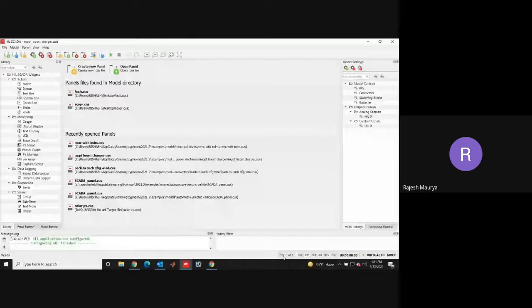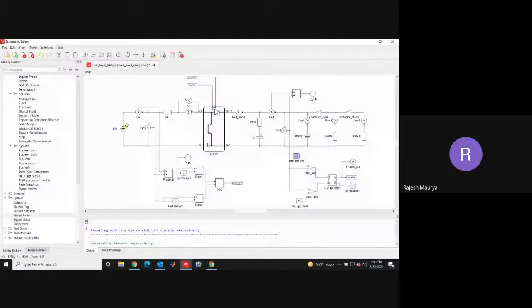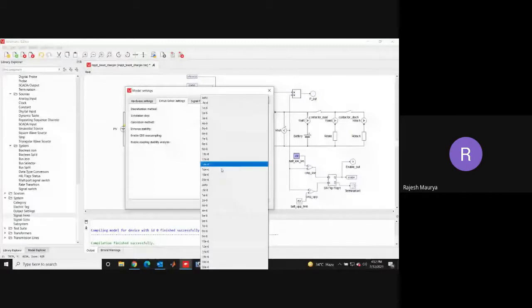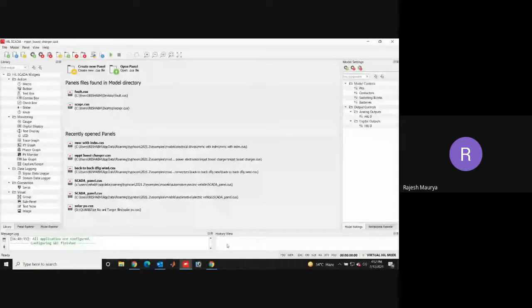Basically, the TSO error. TSO error means time slot overrun. The full form is time slot overrun. It refers to the time step you have defined for your plant part. When you select the new model, at that point you select the time step. I'll just show you. Here, this is your TS for your plant part. We basically select auto. Whenever we select auto, it will choose the best suitable time step and compile the model. So whenever the model goes beyond the time step we have given, and faces issues compiling, then this TSO flag will pop up.